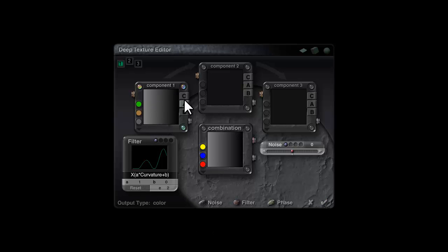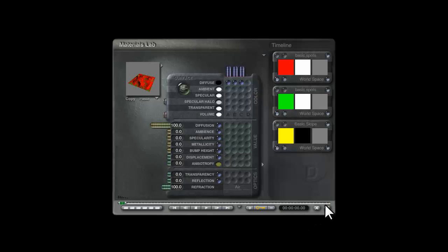To make the issues more apparent, what I'm going to do is increase this value in A, which means the transition zone between white and dark becomes narrower, which means that it'll be more of a challenge for it to smooth between convex and concave, all the various curvature response. This B value here allows me to move the transition zone around, so I'll get it more or less in the middle. So I'll now check out of that.